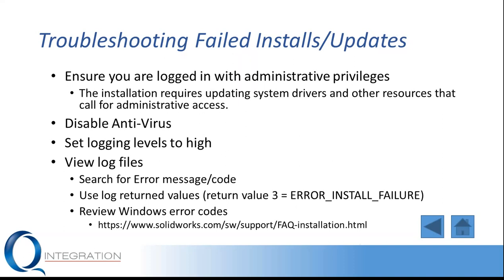And then you should set the logging levels to high. And to do that, you can right-click at the top of the installation manager for SolidWorks, and it'll give you the option to set the logging levels to high. This gives you a more detailed set of logs for you to look at. And typically, if you have a failed install, you go through us, we'll request these logs. You can send those to us just through the email, and we'll go in and we'll take a look at some of the error codes that are being produced inside of there.